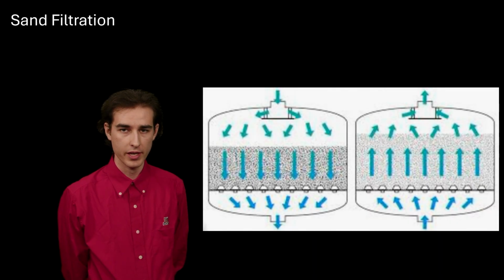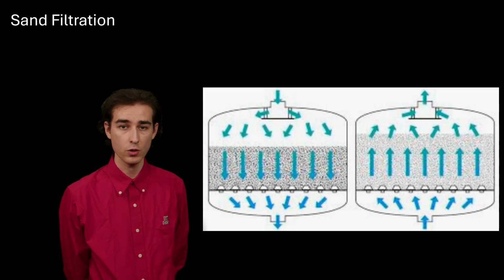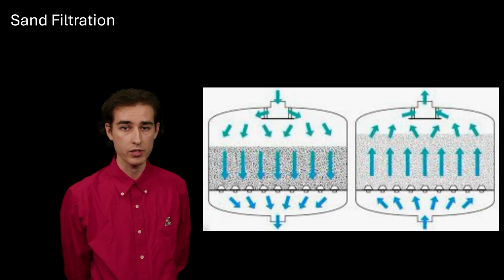The rapid sand filter protects downstream unit operations from conditions adverse to their function and removes contaminants in the feed water. The filter primarily traps solids, biological foulants, and substances which would otherwise not be removed by the ion exchange process or not efficiently removed by the reverse osmosis process. The system utilizes a bed containing fine quartz particles which act as absorption sites onto which contaminants within the water may attach. Particles also physically block large contaminants, such as suspended solids and biofilms, from passing.